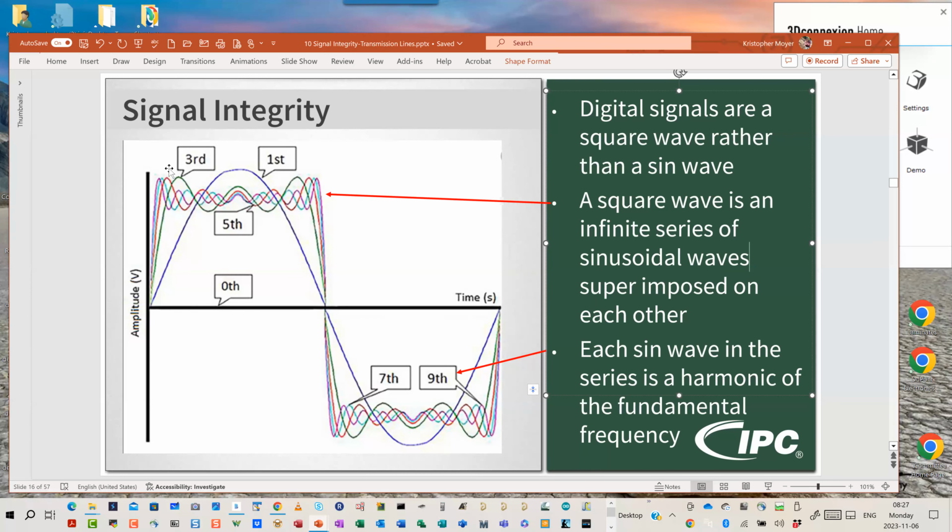And this is also one of the reasons why when you look at square waves on an oscilloscope, the two horizontal portions of the square wave always seem to have some fuzz or some noise on them, but the vertical sections don't. That's because you're seeing the results of this infinite Fourier expansion series right here. Okay?